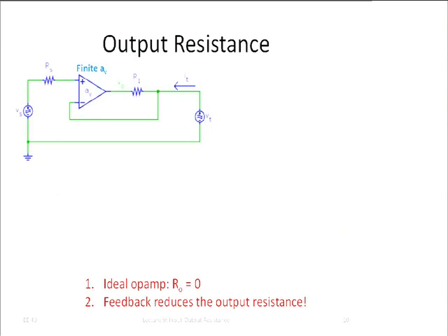So here is an operational amplifier, and the operational amplifier, the triangle that I showed there, is always ideal, except in this case I introduce two non-idealities. The first one is I give it a finite gain. Okay? So here I say the gain is AV, so then the output voltage Vout is the difference between the positive and negative terminal multiplied by that open loop gain AV.